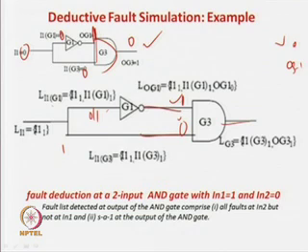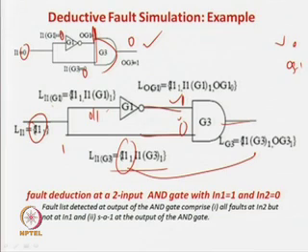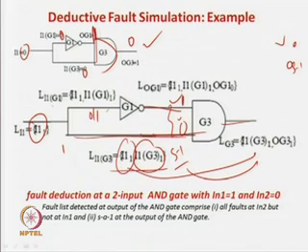So, even if this is a 1, whatever is in this case should propagate over here, but as this fault is affecting both these nets, these things do not propagate. But this fault, that is I1 G1 3 1, that is this net stuck-at-1, is easily propagatable over here, because this signal value is 1. So, whatever is here propagates over here, and this fault does not have this impact. This can be very easily verified.